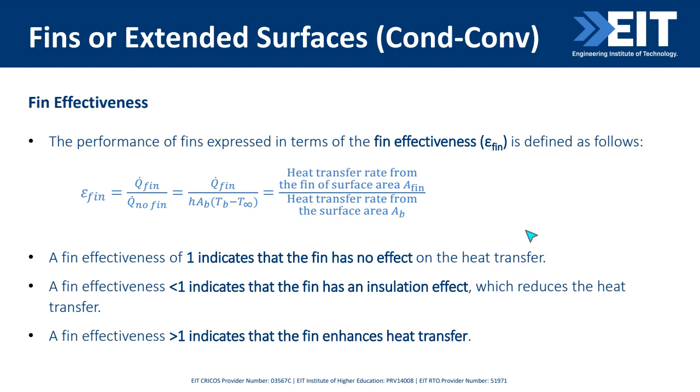Now, the first question that will arise is that when we are adding fins, we're actually increasing the weight, we're increasing the cost of a product, where we're adding material. And usually these materials are copper or aluminum, which are expensive. Copper is definitely expensive. So we're adding cost, we're adding weight, and in many cases weight is not good, like in aerospace industries, automotive industries, or even electronic components, we don't want heavyweight electronic components or heavy automotive vehicles.